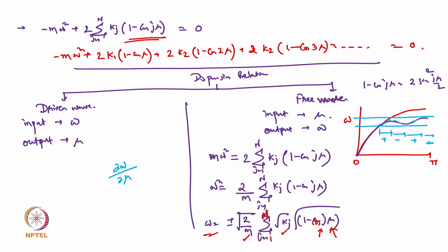So here we can see a coexistence of positive and negative group velocity in the same band of frequencies, and that's a very, very interesting phenomenon altogether. This phenomenon is often called roton-like phenomena. So here the coexistence of negative and positive group velocities can be seen.